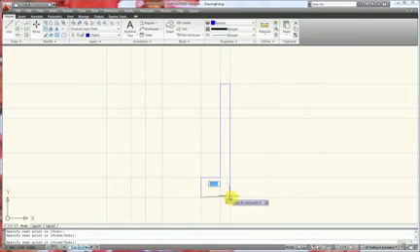It might be helpful since we're pretty much just snapping a 90-degree location, so we're just going to turn on ortho. And now we're going to do the same with this side here. Go from here up to this point, and then I'm going to type in tab 120. Kind of raise your cursor a little bit high when you do that.